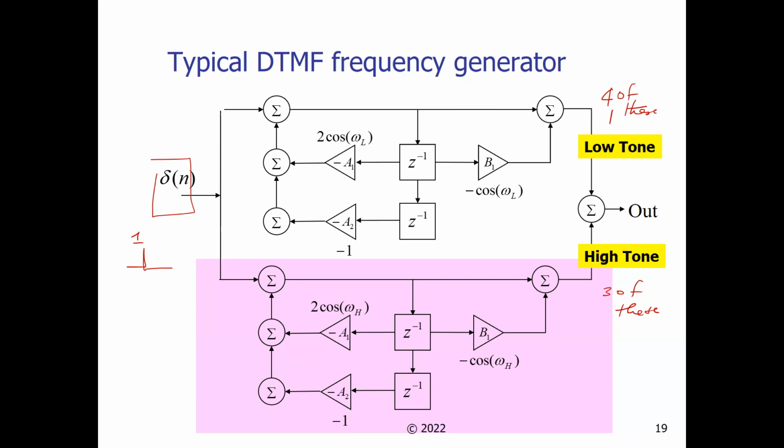So the application of this is that, one, you can generate sinusoids and cosinusoids by looking at the Hn, the impulse response that you want, and then getting Hz from that. Then you can go up and down the frequency range to your heart's content. If you put in the attenuation factor, you get a tone that decays.